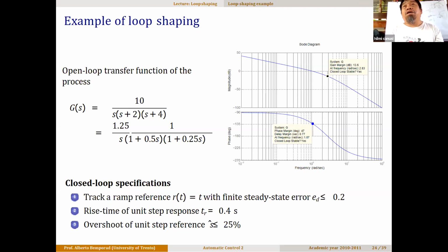It is not a good idea to start with Ziegler-Nichols or Cohen-Kuhn, because for a motor it is not suitable. If you choose KP, KD, KI using Ziegler-Nichols, then you can see how the system will suffer.